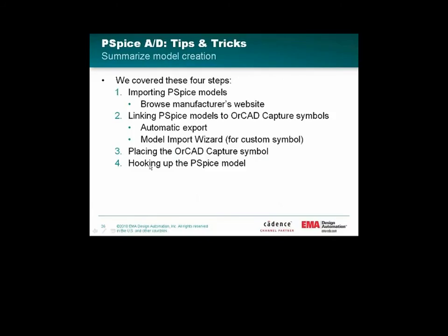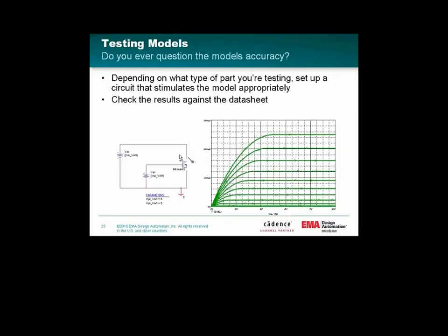That was the steps to import a model. So import a PSpice model from the web, link the model to a symbol using automatic or the custom symbols, in my case the op-amp, place that OrCAD symbol on your schematic, and then hook it all up.